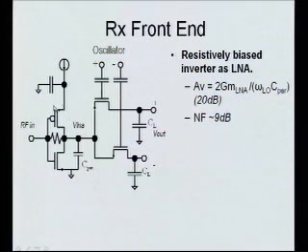So I use an inverter basically because I couldn't use inductors because they weren't any good in the process. So I need to have some sort of current source here anyway for a high impedance load from my common source. And that was going to be a PFET anyway. And then if I'm going to have a PFET, I may as well get a little bit of gain out of it by making an inverter. This is not a 3-to-1 scaled inverter. It's actually a very different scale factor. There's an optimum mix of capacitance and GM that gives you the scaling that I basically did in Excel.